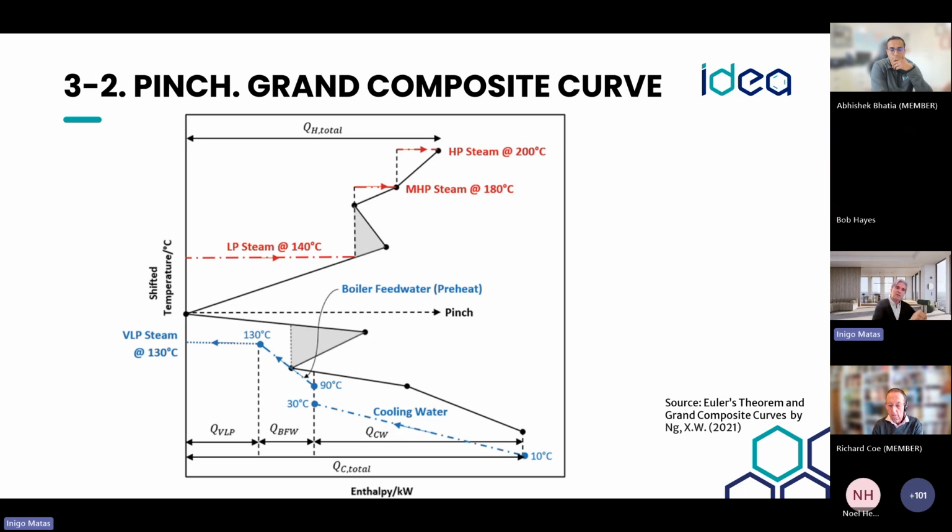This is from the composite curve. We can produce what is called the grand composite curve that we can see here. This part in the center will be like the pinch point.